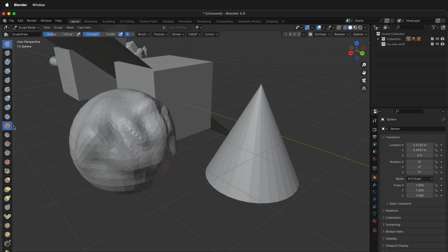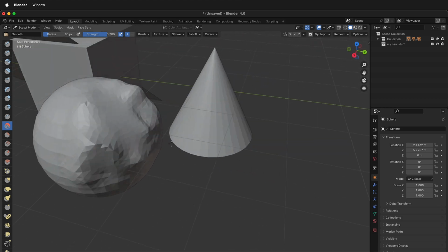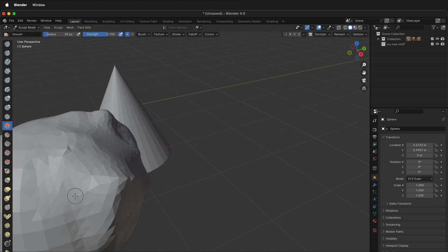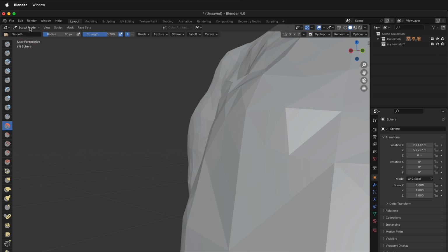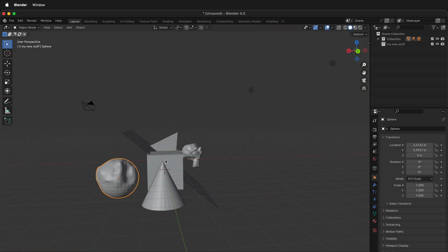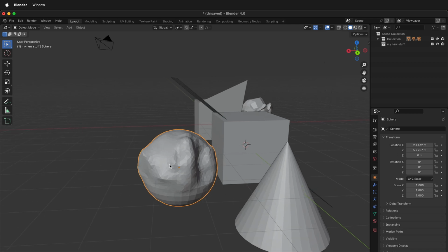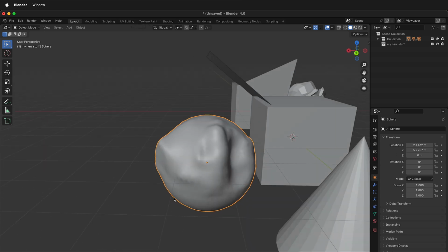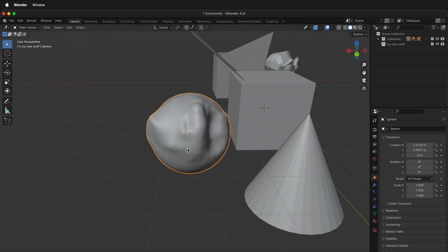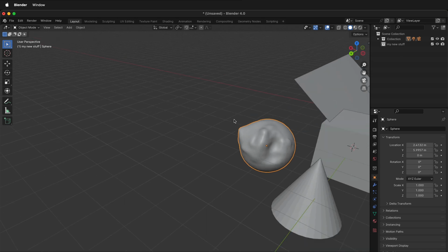I can get the smooth tool. So now I can go ahead and smooth out these shapes. I can move my radius down so it's not going to affect everything as much. And then smooth out those objects right here and just keep sculpting and moving around. So this is a great way to make objects as well. And if I go back to object mode and then I orbit around, you can see how it's kind of lumpy. This is a time that if I click Shade Smooth, now we can see what's going on with our shape. So very, very great way to make objects in Blender.